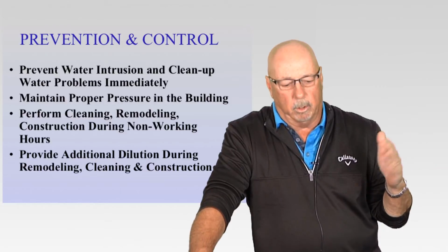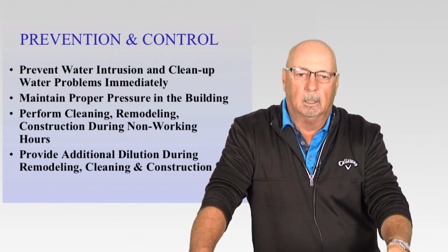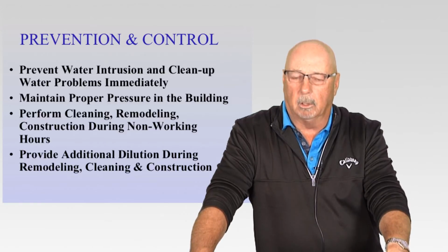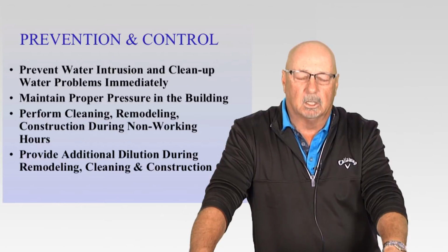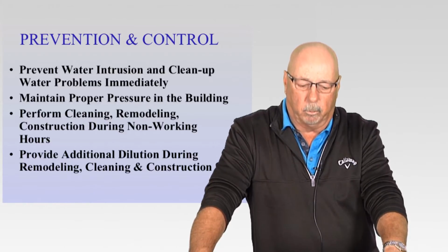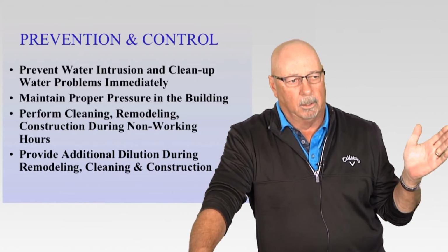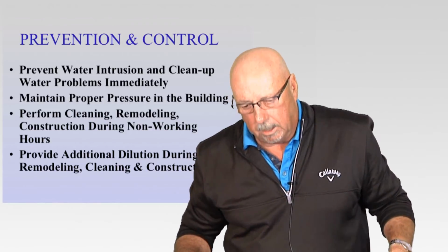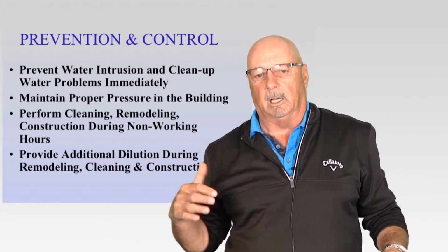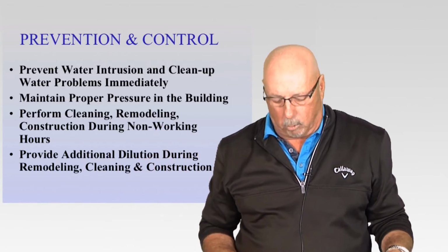Whenever we do remodeling, or if we're going to do massive cleaning of the building and so on, try to do those in off hours or on weekends, in times where there is minimal occupancy of the building. And whenever we're doing those kinds of activities, if we're going to have some construction going on, or painting or some kind of special thing, during those time periods we want to adjust our ventilation system to bring in more outside air so we have more dilution air.